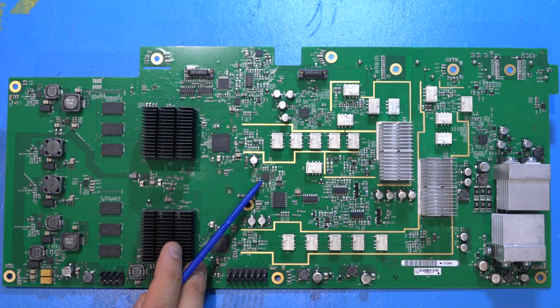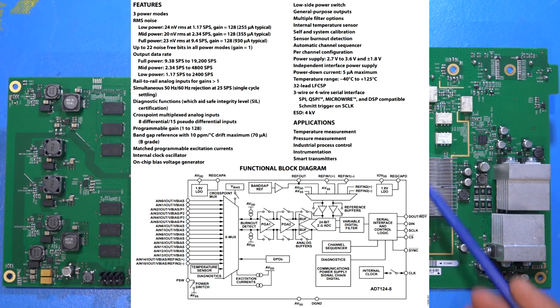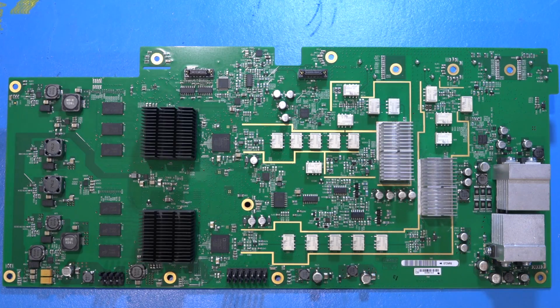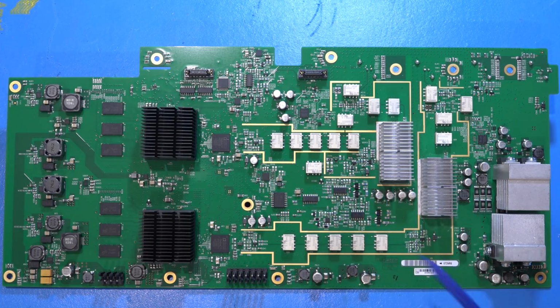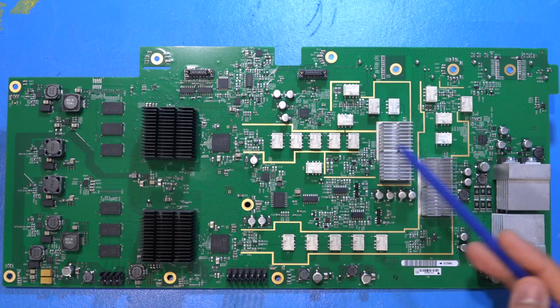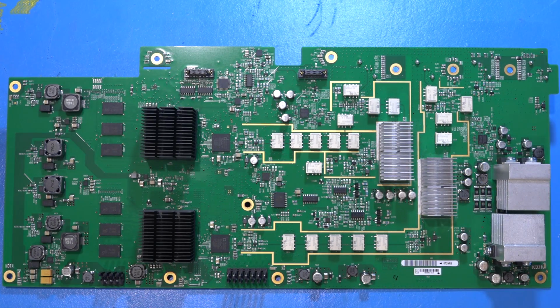There is also an 8-channel 24-bit delta sigma ADC here, which is used to sample potential thermal information, offset information and biasing information fed back to the main controller. So you can get an idea of what's going on, and potentially these guys are all working together in some kind of feedback to get the highest performance from the outputs and apply the DCs required. So that common section you can see is used on both of these, and then I'll show you the other side of the board so we can see how the outputs are taken.